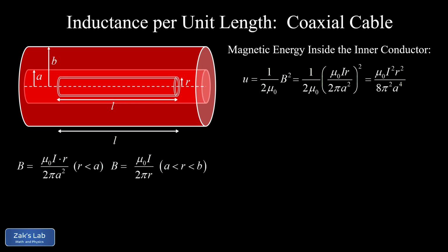This allows us to find the energy contained within the shell wall by simply taking the magnetic field energy density and then multiplying by the incremental volume contained in the shell. So there's a general expression for an increment of field energy. I wrote that as dU. So that's an increment of magnetic field energy captured within this thin shell wall. And now we have to put in the details about the energy density and the volume of that shell wall.